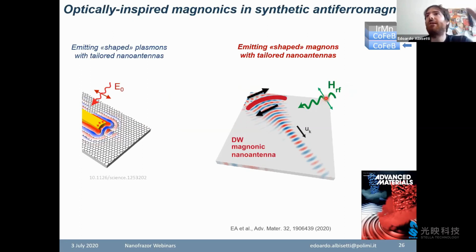And if we illuminate the whole chip with a uniform and not highly localized oscillating magnetic field in the gigahertz range, then this field happens to couple very well only with the structure that we wrote via SPL, so with the domain wall, and actually sets this spin texture in oscillation. And the oscillation of the spin texture is what actually emits spin waves.